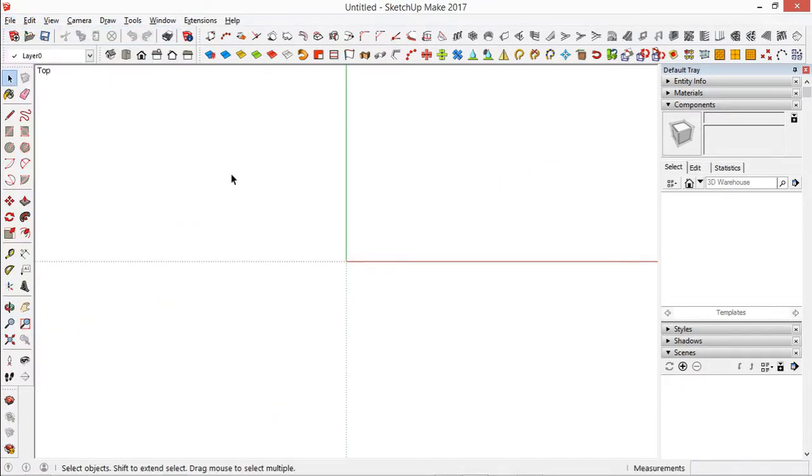This time, we will draw new objects using Line, Two-Point Arc, and Arc commands. Click Line command and start drawing the object from the point as indicated in the figure. After drawing the second line, click Two-Point Arc. Start the Two-Point Arc command from the last point and on the second point define the length of the arc. Finish the command by clicking to the height of the arc as shown here.